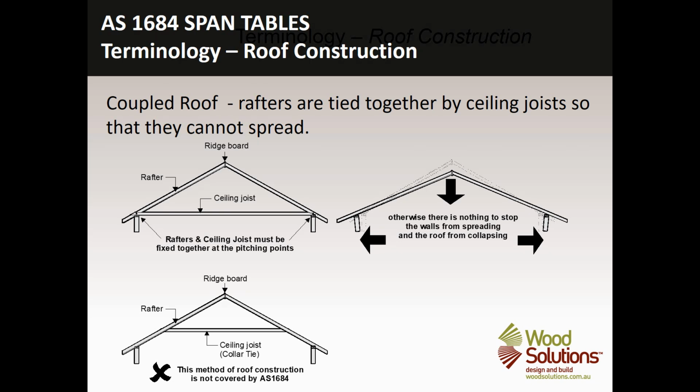Have you ever seen that on buildings? So it's basically just once again the introduction of an arch. Because we don't actually need this material in here, and then we curve that as well. So yeah, just a little bit of trivia. But that's how they stopped their wall frames from spreading and rotating under load of the roof when the roof wanted to push the walls out.